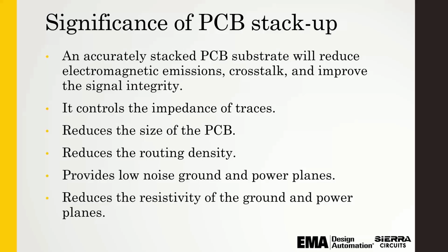In summary, the significance of a PCB stack up: a good stack up will reduce your electromagnetic emissions, crosstalk, and improve your signal integrity. It definitely controls the impedances of the traces. You can reduce the size of your PCB. You can control your routing density. So these are all the significance of PCB stack ups. Of course, having low noise ground and power planes, these are all super important for PCB stack ups.